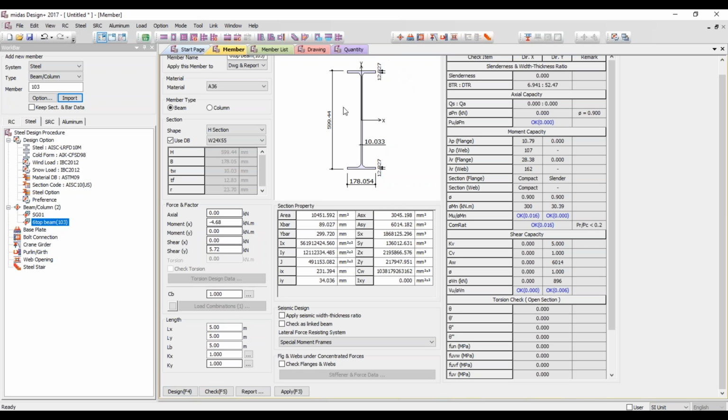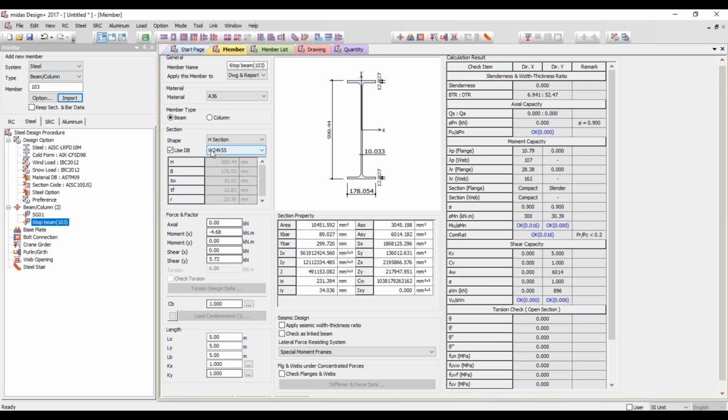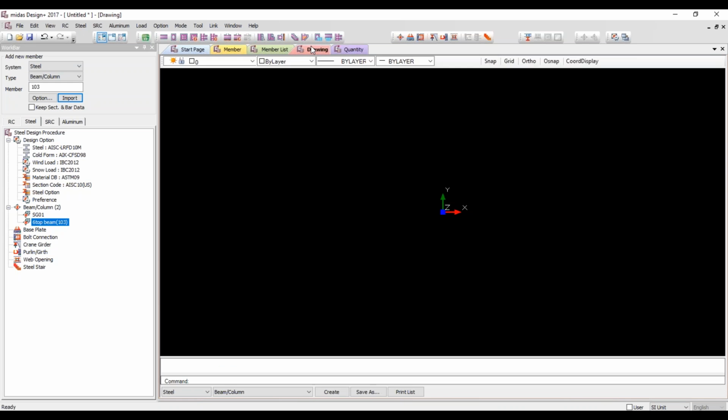So now we see that the section has actually been dramatically reduced in dimensions. We're using a lot less steel, but we're still passing all the requirements, the moment capacity and the shear capacity. And so the program is telling you that you should be using a section of 24 by 55. So you could go back to Gen and change the dimensions and run the analysis again in this kind of iteration process to get the optimal. Specifically for steel, you really want to use the least material possible, so this tool is great for that. And lastly, you can get a quantity report and a CAD drawing, all within Design Plus.